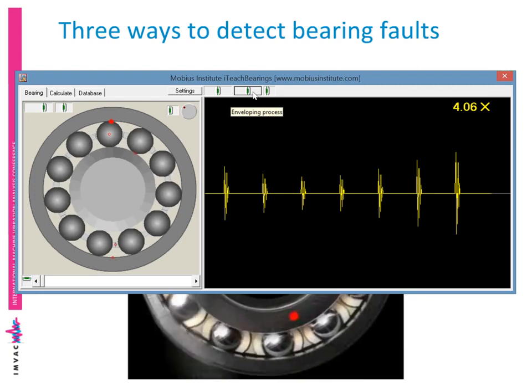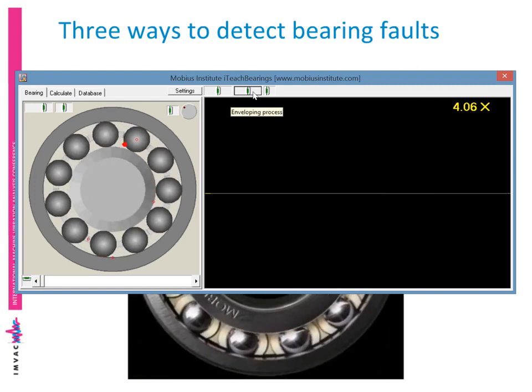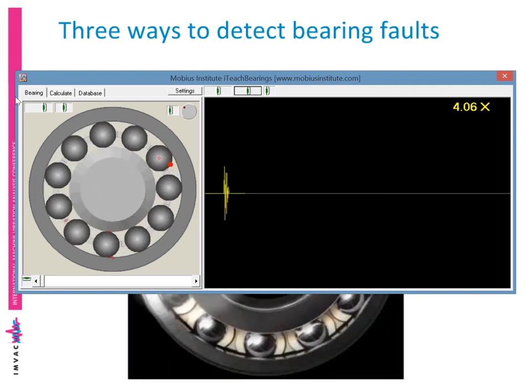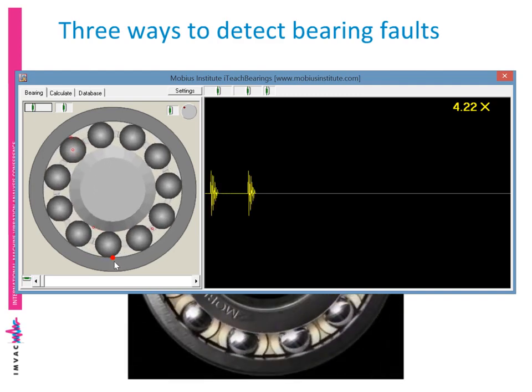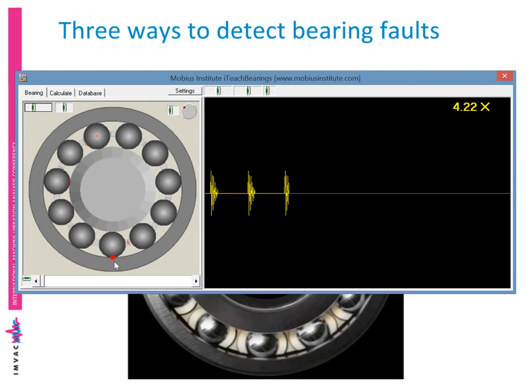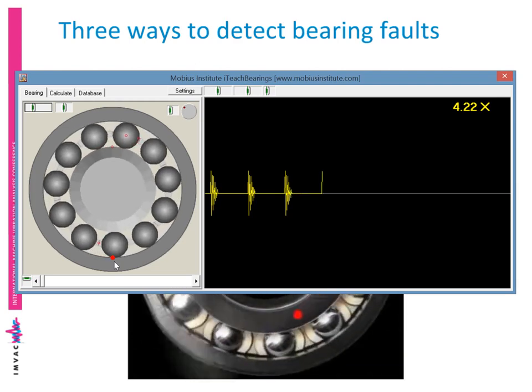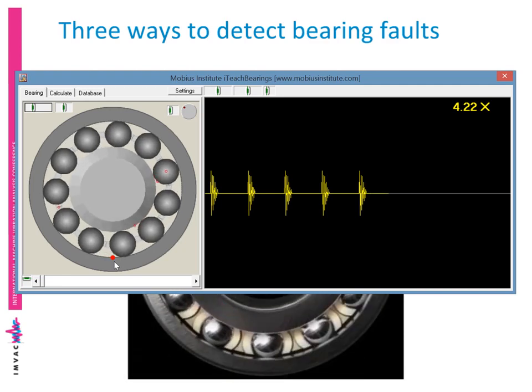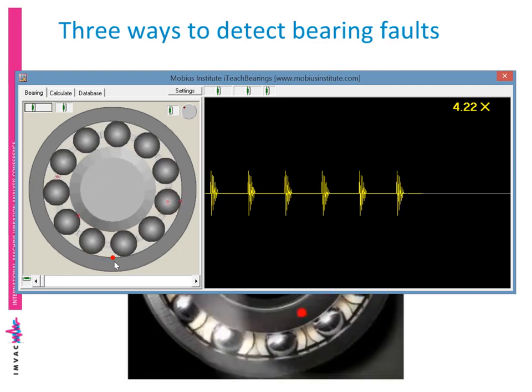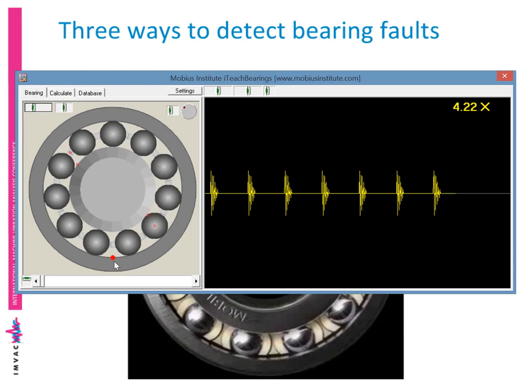And then there are techniques like peak view and shock pulse and so on that are specifically designed to detect this type of fault condition. They specifically look for the high frequency vibration, they isolate that with filters and so on, they use rectification and all these sorts of things we don't really need to talk about right now.